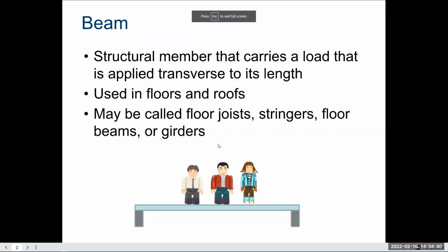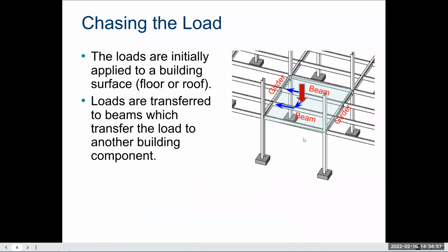So first off, when we talk about beams, these are structural members that carry a load that's applied transverse to its length. So meaning that if the length is this way, transverse coming down along it. Oftentimes used in floors and roofs, and sometimes you hear them as floor joists, stringers, floor beams, or girders.